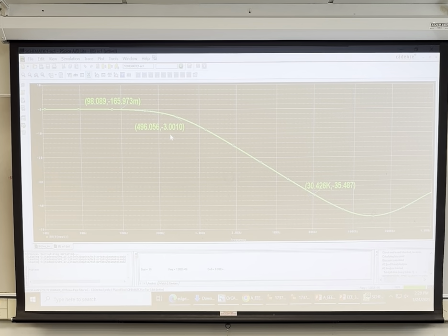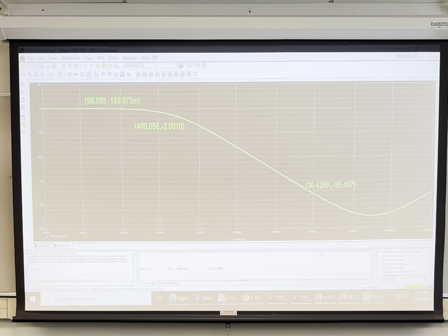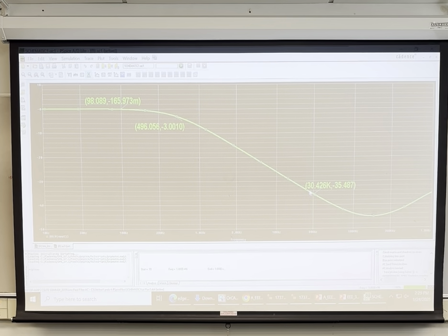So depending on the last digits of your Z number, you'll be ready to guesstimate a cutoff frequency. It's important to have that gap. If the cutoff is too close to your desired, you're going to reduce your desired. If it's too far away from the interferer, then the interferer will move back up and be present in the system.